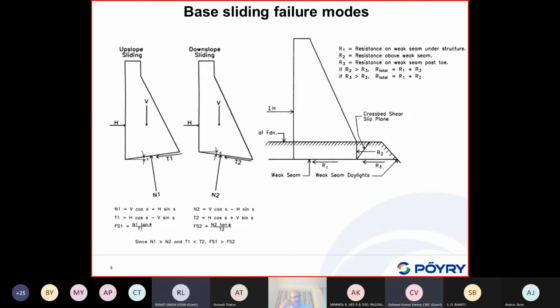Now, if we look into the dynamic stability, we look into kinds of failure modes which we also consider for static stability analysis. Static stability analysis is basically sliding stability under water load. Depending on your dam, if you have an upstream slope like that, this would be favorable. It stabilizes a movement here. This one would be downslope sliding.